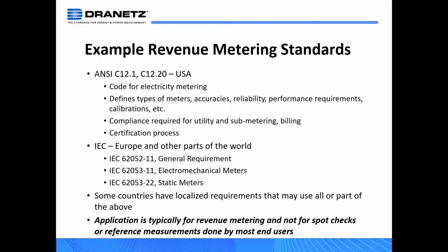So we're not talking about just the meter itself, but any transducers that are used, CTs, possibly PTs, can work over the voltages, the currents, and the environmental considerations and temperature and humidity and things like that. So it's a little more complicated than just the meter itself. And some countries have localized versions of this. I know, like in Europe, there's the MID requirements. I'm not quite sure I recall what MID stands for, but other European countries take those MID standards and make their own versions of that. So it does get a little more complicated.